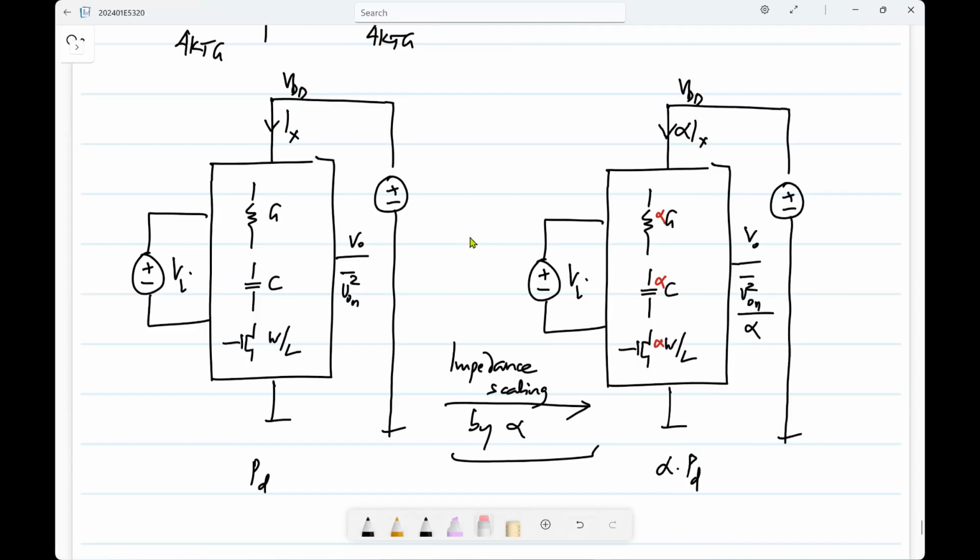If they have the same SNR and different noise, one also has a smaller signal level, right? So these are now two different circuits. So now it's hard to figure out what you're comparing. Of course, the design is different. I could design some circuit and you could design the same function with a lower power and lower noise if you are clever enough, right? So that's not what we are comparing. We are comparing just scaling the same circuit to have lower noise. But there are fundamental relationships between power dissipation and noise that I think is part of your next assignment. You can work it out.